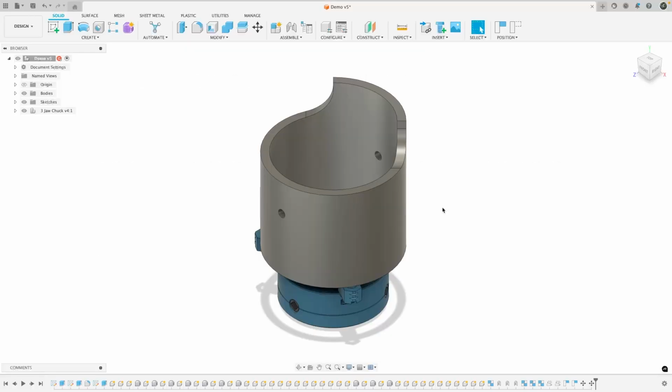Okay, I have a sleeve modeled up here. It has 2 half-inch holes in it and a cutout around the top. These 2 half-inch holes, we will actually get a problem. The post processor will try to still output G68.2 on the hole positioning, so we are going to have to go in the post processor and disable it.